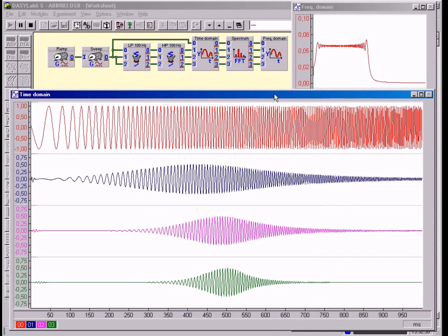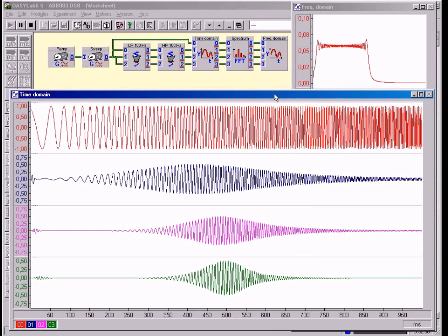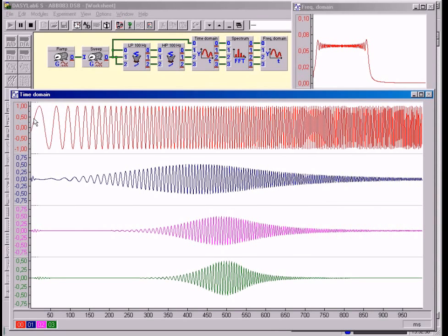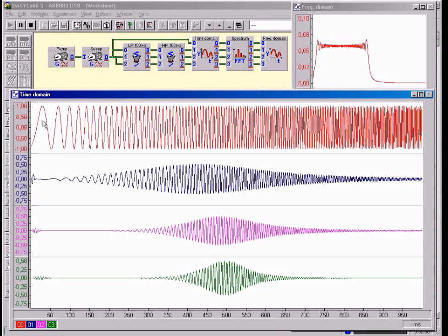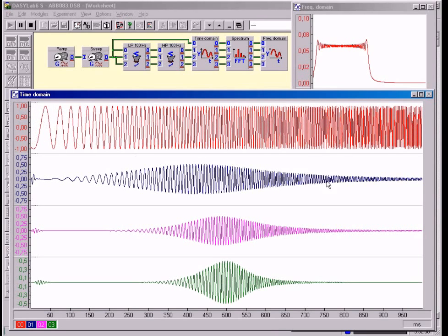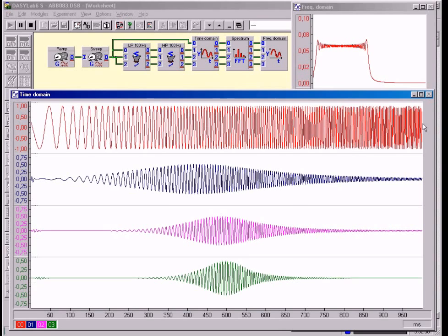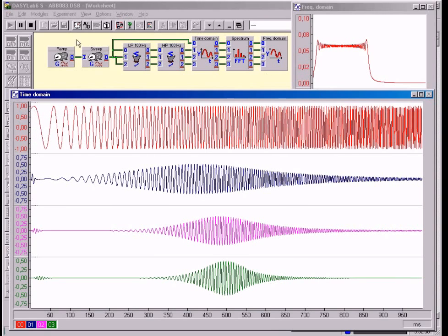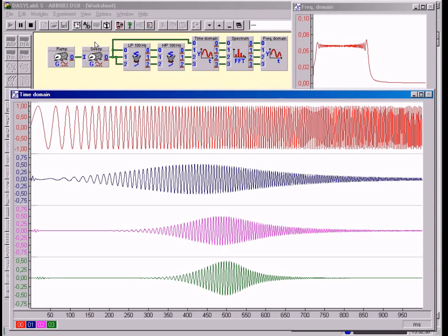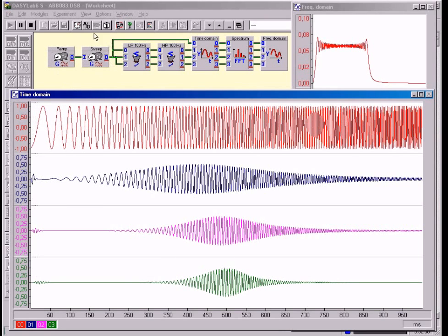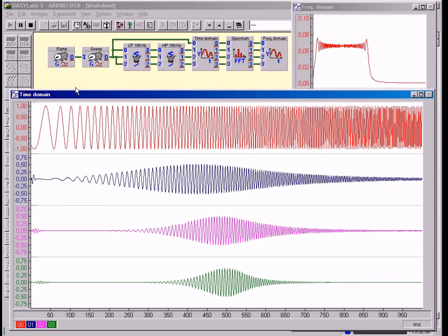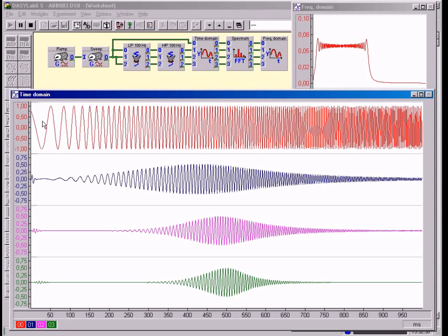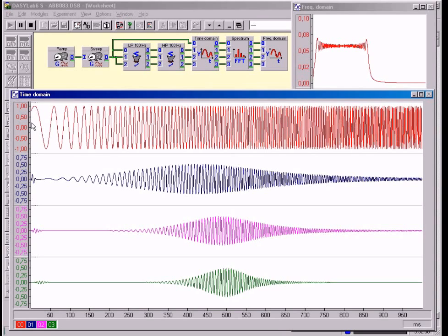Instead of setting the frequency range continuously by hand from the lower starting frequency F start to the upper stop frequency F stop, this is carried out in the instrument by means of a voltage-controlled oscillator. Thus, the circuit is gradually tested with all the frequencies of the frequency range with which we are concerned here.